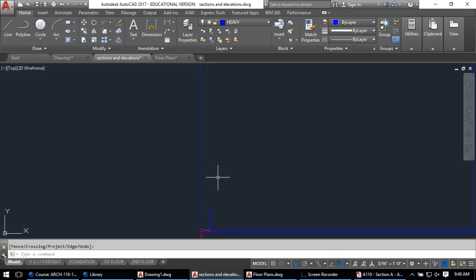And I'm going to come up to the top, and I know I have the joist coming through. I'm going to have a double plate up at the top of 2x6s. So I'm going to take this 2x6 and copy it up right on top of there, because this joist is going to come and sit on that element there. And the drywall will come all the way through.